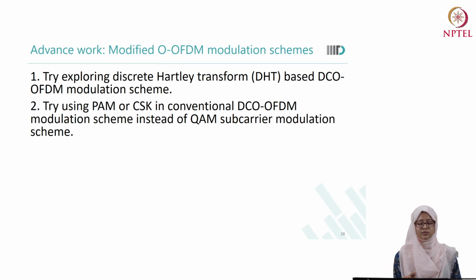These are the advanced work one can prefer to do. What about going ahead with a modified optical OFDM modulation scheme? You can try exploring discrete Hartley transform based DCO-OFDM. An interesting part of the discrete Hartley transform is that it gives real output for real input data.